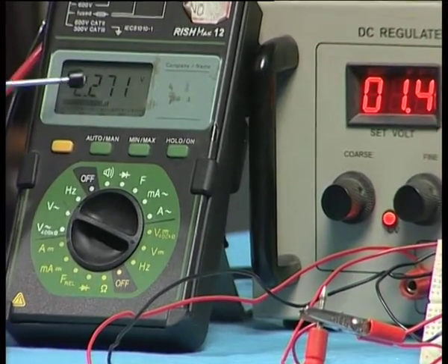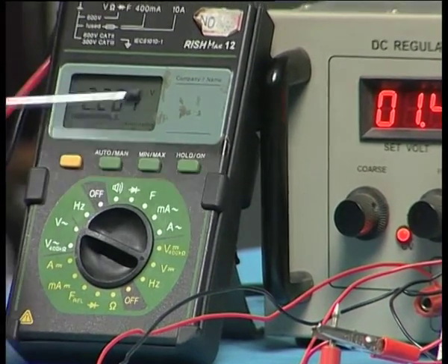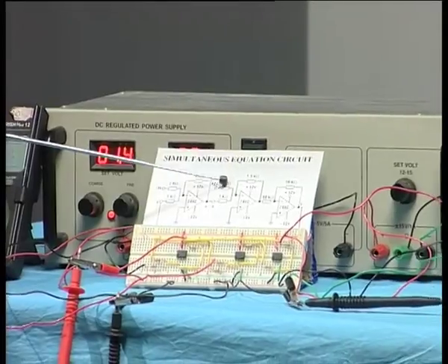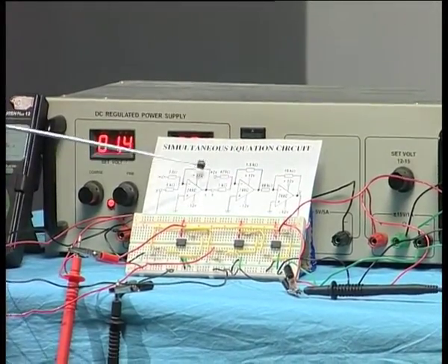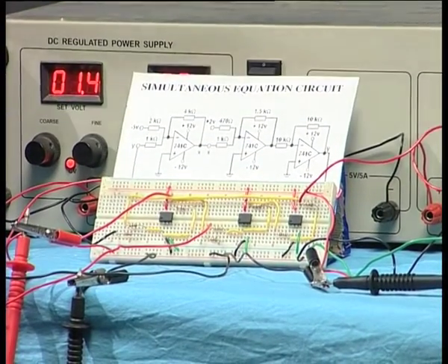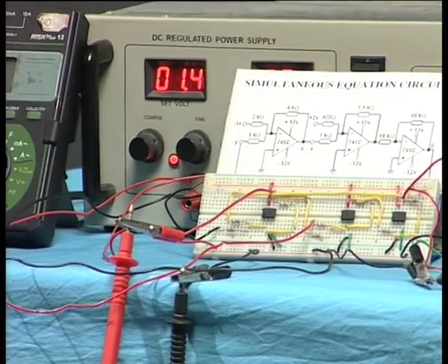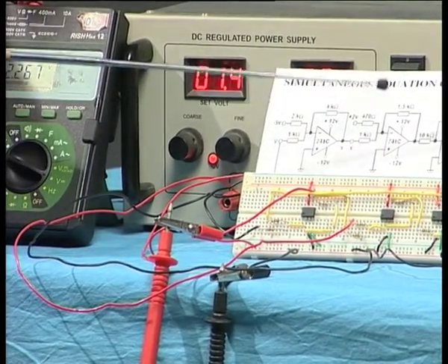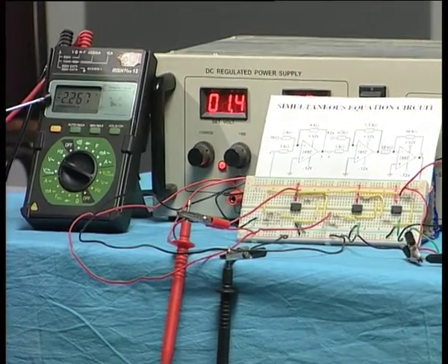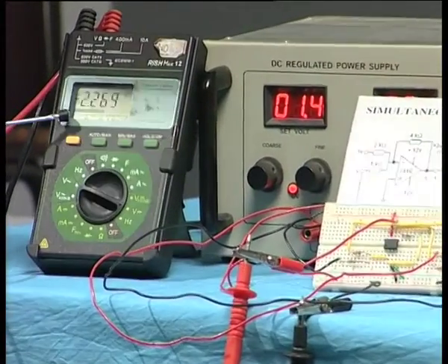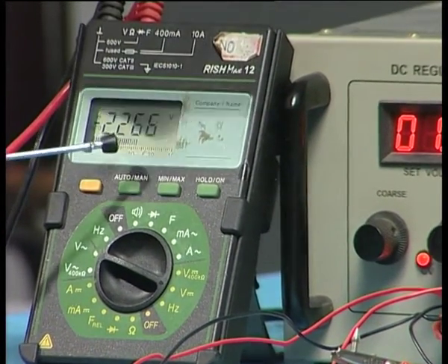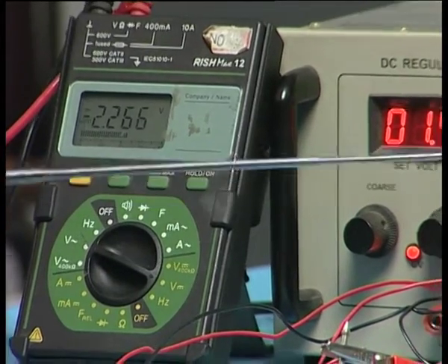There is a slight variation here, it should be precisely minus 2 volts, it is not, because I have not used very precise resistors here. For example, I have used 470 ohms instead of 500 ohms, and all these resistors will have some small variation because of the tolerance, and therefore there is some residual extra voltage that comes in here, minus 2.2. If I use very precise values of resistors at every point and measure, I will get a very precise value of minus 2 volts. I do not know whether you are able to see the minus sign here, it is minus 2.2 volts, that gives the solution with reference to x,